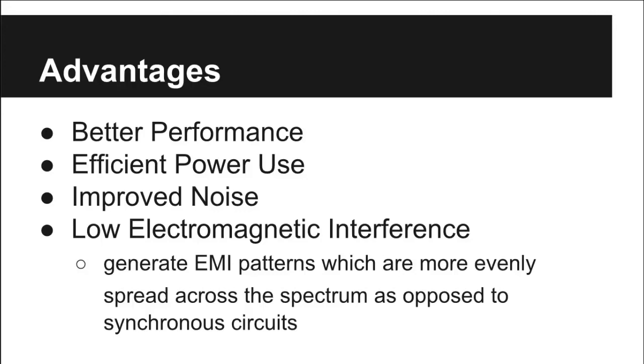Additionally, power use is also decreased since we don't have to account for the clock continuously pulsing for the entire time that the system is up and running. Only active functional units consume power, while inactive units remain in a standby mode. This means that we aren't wasting power on units of the CPU that aren't being used, versus having the clock signal being fed to them and present every time and everywhere in the synchronous design.